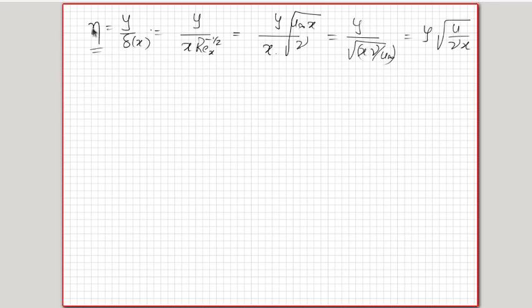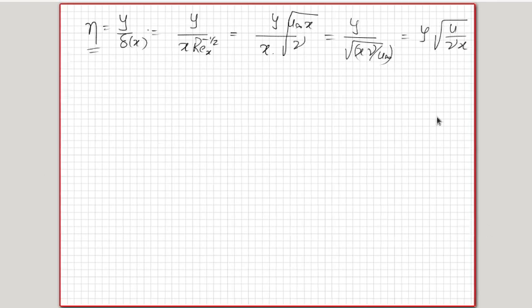So if I derive that, then in order to unify the velocities u and v into one, we use what is called the stream function psi. Okay, so what is the stream function psi? Stream function psi is defined in such a way that del psi by del y is u and minus del psi by del x is v. So by defining this stream function, we ensure that the continuity equation is automatically satisfied.